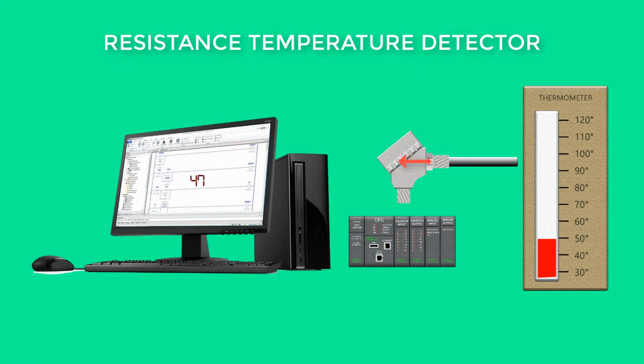Resistance temperature detectors, or RTDs, are designed to produce an accurate and linear temperature value. RTD analog input modules on PLCs use electronic devices to convert the voltage values created by the RTD into digital values. The digital values are used by the PLC software for programming temperature control and temperature monitoring. An RTD is an important device for temperature control and temperature monitoring in automation and process systems.